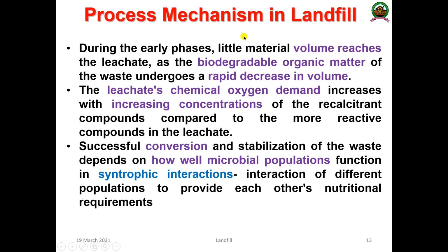Okay, so once this particular process happens, the chemical oxygen demand of the leachate or the waste material will increase with increasing concentration of the recalcitrants, compared to the more reactive components in the leachate. So the successful conversion and stabilization of the waste will depend on how the microorganism population acts in a coordinated way, especially in a syntrophic interaction.